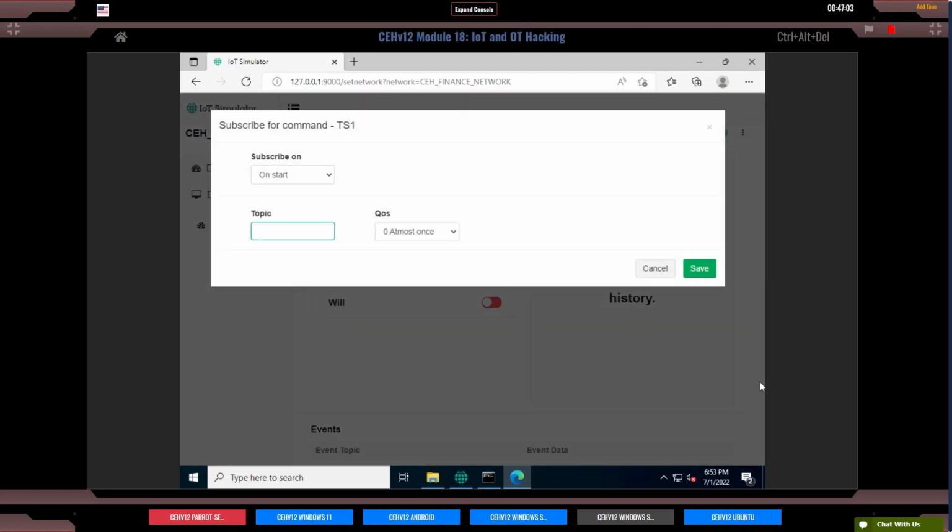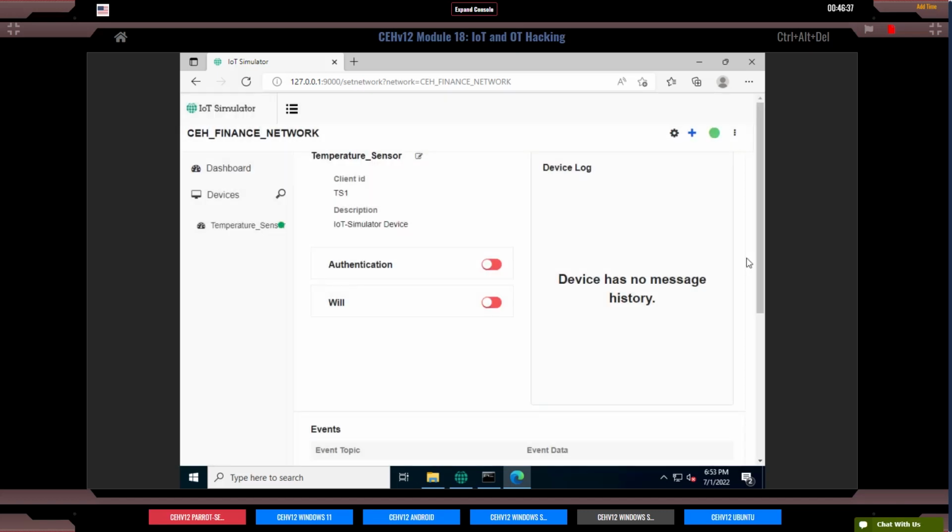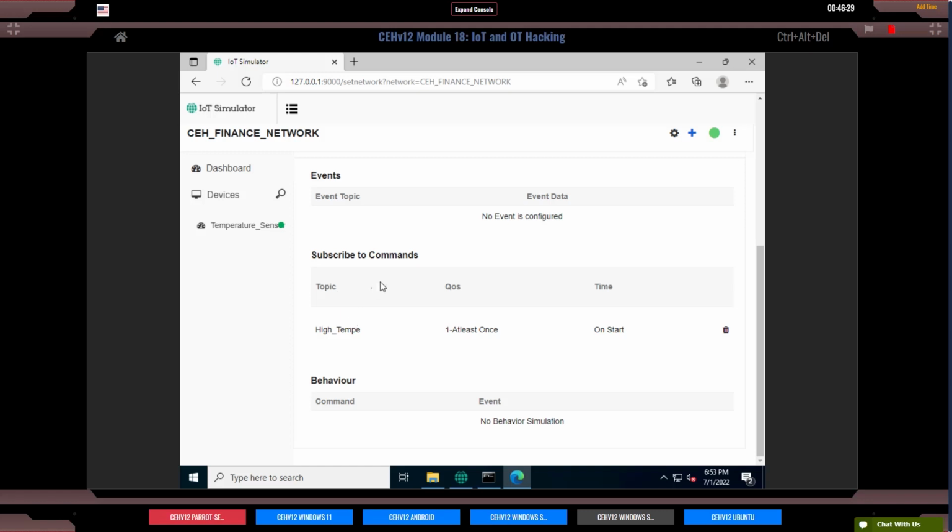The subscribe for command TS1 pop-up opens. Select on start under the subscribe on tab. Type high temp under the topic tab and select at least once. All right, click on Save. All right, scroll down the page. You can see the topic added under the subscribe to commands.